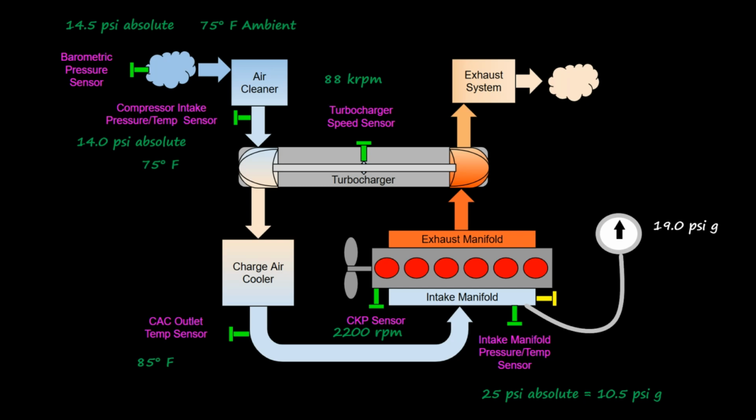Even though the actual mass airflow of 75 pounds per minute, which we had in the previous example, hasn't changed, the ECM is now going to underpredict that value of mass airflow, since the density of the air we're measuring in the intake manifold is being underpredicted because of the lowered manifold air pressure measured by the faulty intake manifold pressure measurement system.